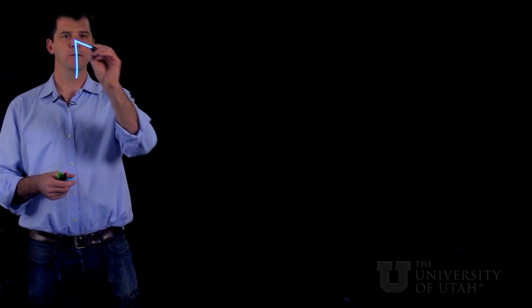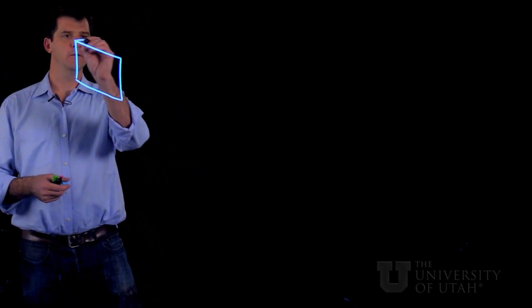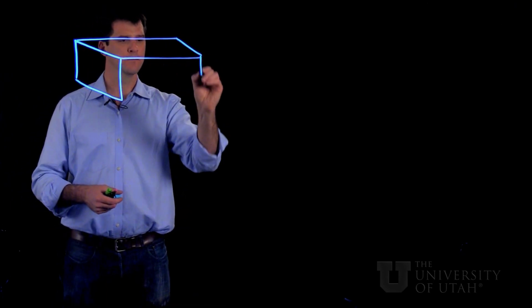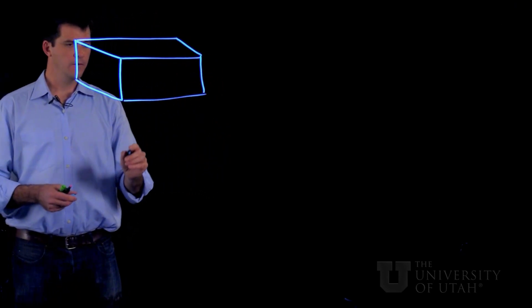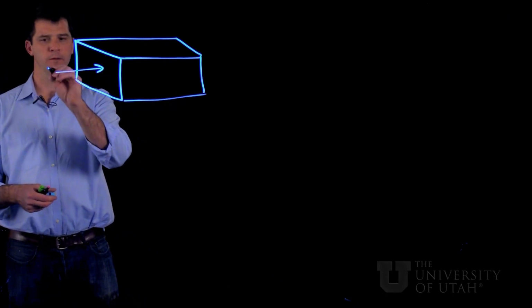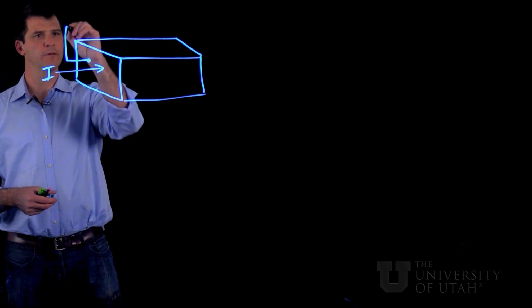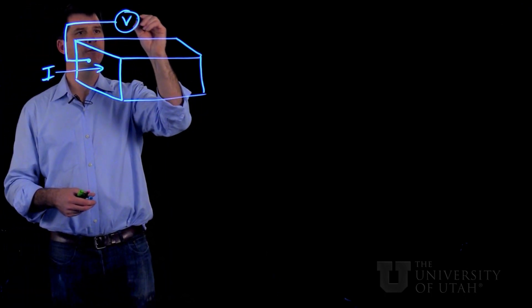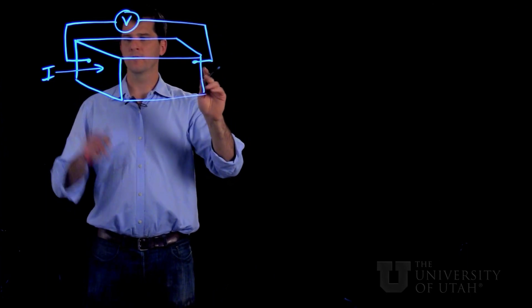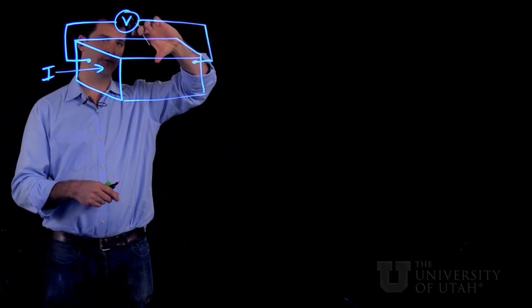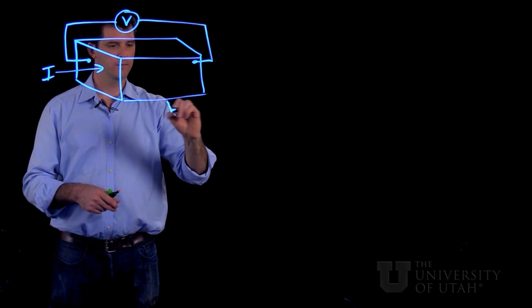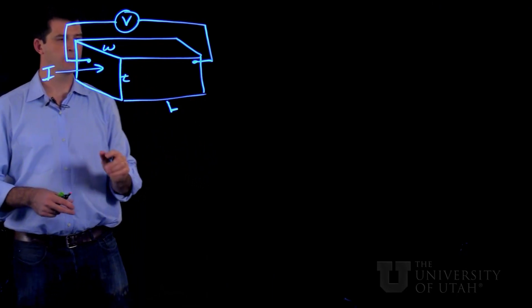So now let's look at two more aspects having to do with the Hall effect. The first is the use of the Hall effect to determine the mobility. But you need to combine two experiments, actually. You need to combine a measurement of the resistivity along with a measurement of the Hall effect voltage. So we'll return to our same chunk of semiconductor, and to do a resistance or resistivity measurement, we measure the voltage from the ends through which the current is flowing instead of the transverse voltage, which we measured for the Hall effect. So we'll use the same geometric parameters.